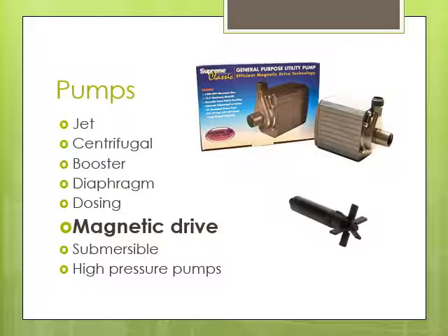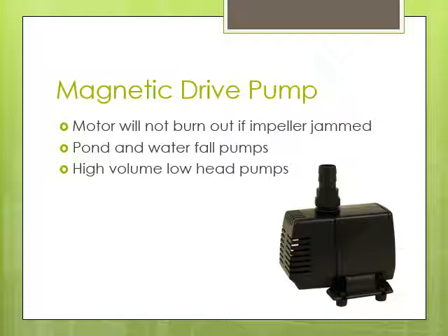Magnetic drives. This is an interesting one. These are typically low pressure applications. The motor is actually sealed and waterproof, and then there's a plastic cartridge with magnets that sits inside and spins, and it's lubricated by water. So these are popular in ponds. In the greenhouse, we see them stirring nutrient solutions to keep them suspended. I've seen them in deep water culture, dropped everywhere to circulate.